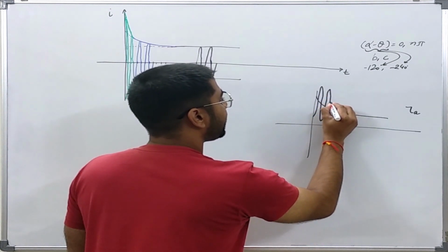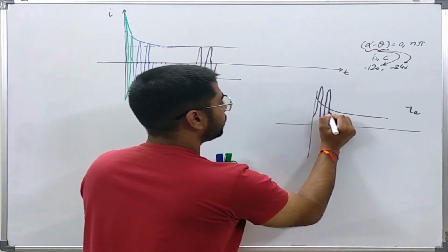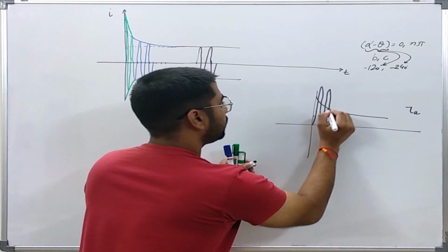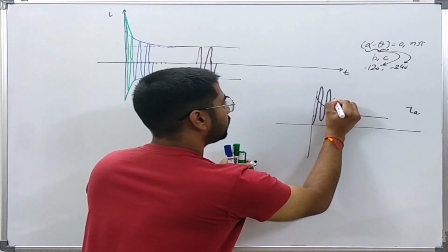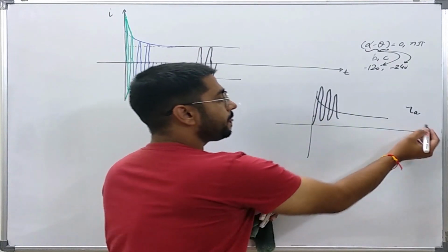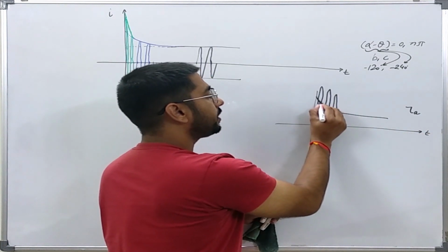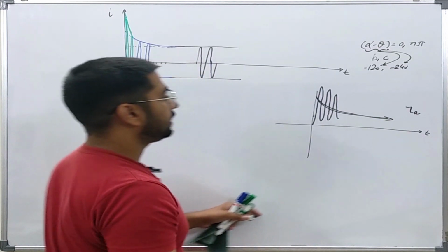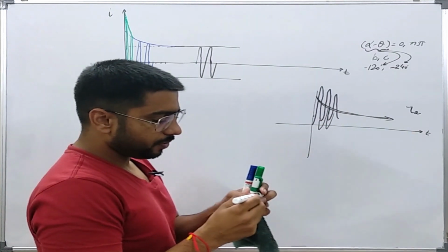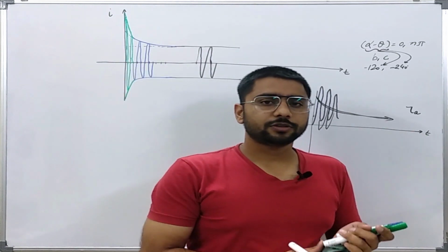We might get some current like this, something like this. That is, the currents might not be symmetrical about the t-axis. They will try to be symmetrical about this DC decaying current. These can even cross this line depending upon various magnitudes. So the currents in other phases will not be symmetrical about the time axis. This point should be noted.